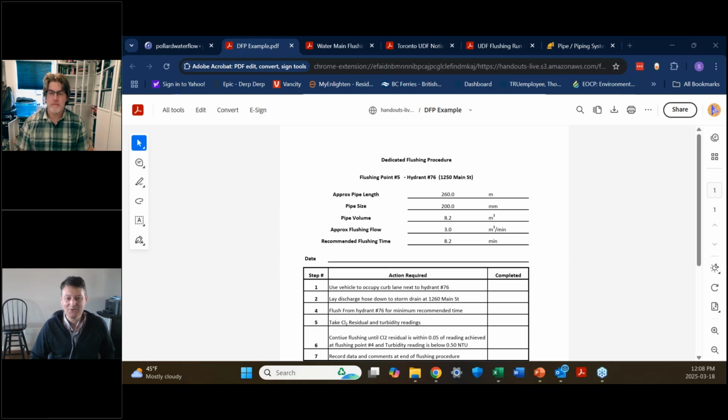Okay, here we go. So Gary asks, if you are a micro small water system on a permanent boil water advisory, is flushing of any use? Gary, yes, 100%. Even if you are on a permanent boil water notice, flushing is not the only thing that's going to get you off that notice, but flushing on at least an annual basis is going to help with that debris that might be building up in your distribution system. And if you can meet those high scouring velocities, with any biofilm that might be in your pipe, it's not going to obviously get you off that boil water notice, but it's going to be one of the tools that you should use to try to get the best water quality in your system at all times.